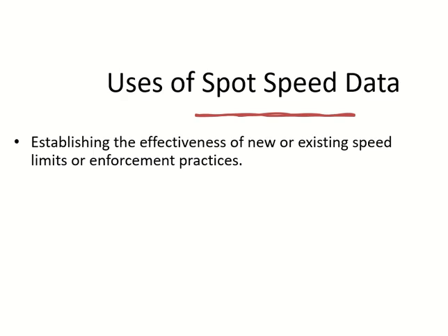So your speed limit will not be effective if you are not fulfilling the expectation. Most of the drivers will go over it, and you have some of the blame for it. Yes, the driver should follow, but you are going against the expectation of the driver. So how to know the expectation of the driver? You do spot speed studies.